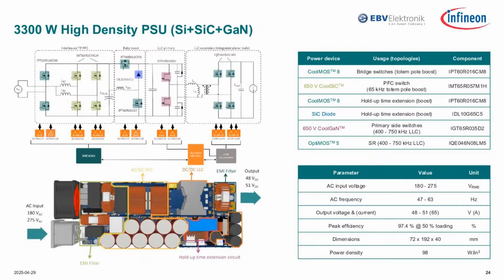And third, even if we try to increase our switching frequency, yes, for sure we can reduce our input inductor, but other components still keep a certain volume, for example our output capacitors and also our EMI filter. So to increase the switching frequency in the PFC stage, we need to consider a balance between the EMI and the output cap for the hold-up time.